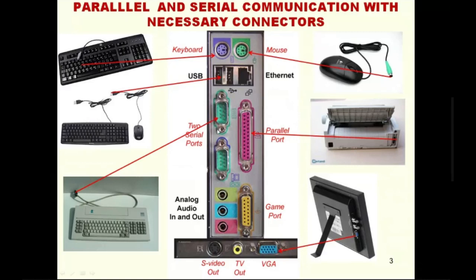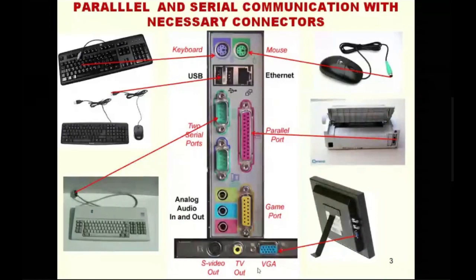Normally, we come across the word COM. This is called the COM port, which you call a 9-pin D-type connector, because it looks like the letter D, with 9 pins in 2 rows. The first row has 5 pins, and the second row has 4 pins. So 9 pins in 2 rows is a COM port, which is called the RS-232 port. This was the first communication port, introduced long back. Now laptops are coming with the HDMI protocol, and some of the projectors have a VGA port. So now we normally use a VGA to HDMI protocol converter, that small cable.